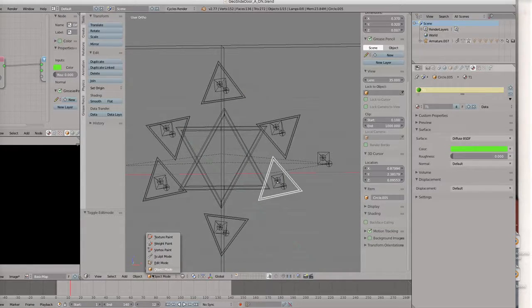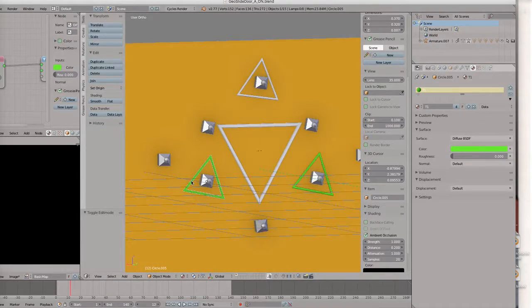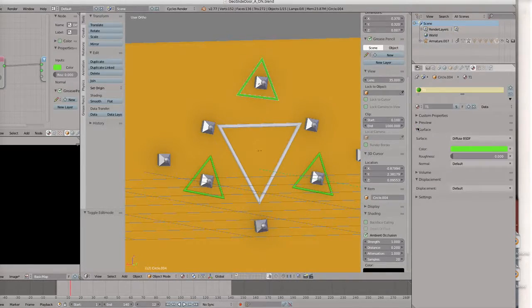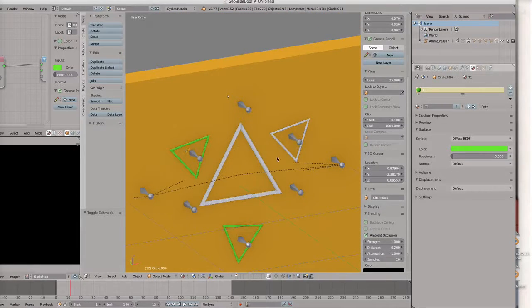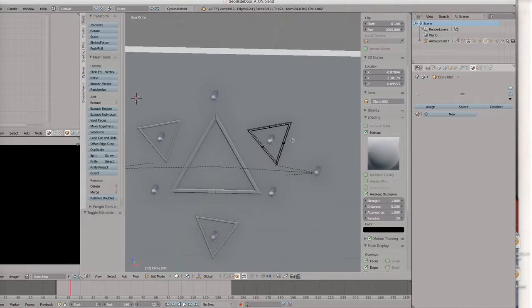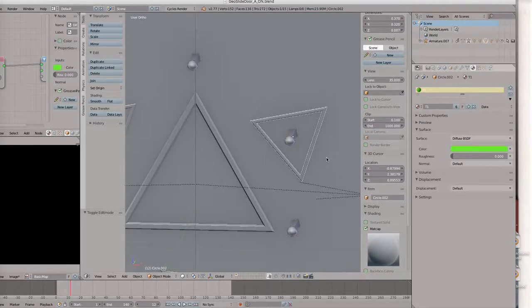Yet a lot of times it will work just by selecting it and changing it in object mode. A lot of times this will work. Other times, if you take it over into Unreal and for some reason it didn't seem to work, like you'll go to assign the material and one of these triangles will not have it, then you might have to go in, like I said, and play with it a little bit, finesse it.